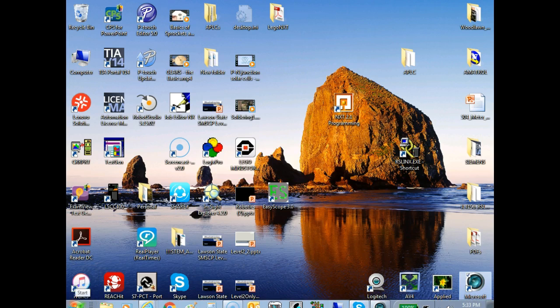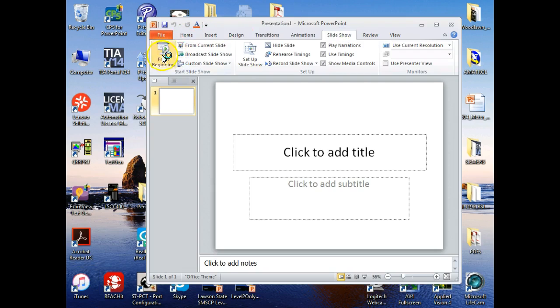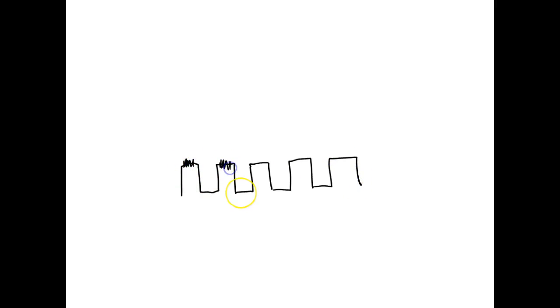Okay, so I've got a digital pulse. So I've got a string of, we'll just put a clock up here. Well, how would I synchronize with something that's that big? I mean, how would I synchronize with a high when it could be high for a certain amount of time, right? And how can I synchronize with a low if it's going to be low for a certain amount of time? But how many edges do we have? We got 1 edge, or we actually got 2, right? I could synchronize on a rising edge, or I could synchronize on a falling edge, because those occur at precise times.